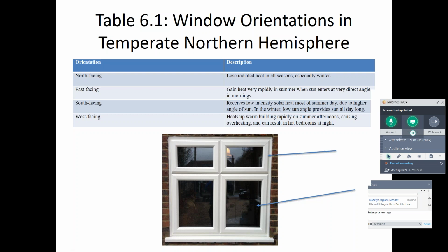The bottom picture isn't really accurate to the concept. I just wanted to have some type of visual, so while I was talking you didn't get completely bored. But what I wanted you to focus on is there's upper windows in a building. Now pretend they're not together. We just have a high upper window in our building, or we have a low window in our building. If you put your windows at the top of your building, you are setting yourself to have a good horizontal amount of light. So like I could have a desk below that I'm hand drafting on, and because they're high up here, I'm getting enough cast light where it's not completely directly on top of me, it's casting at an angle above me nicely.